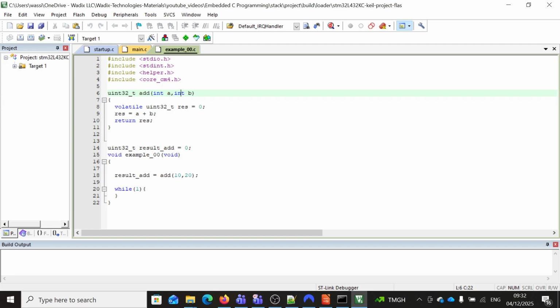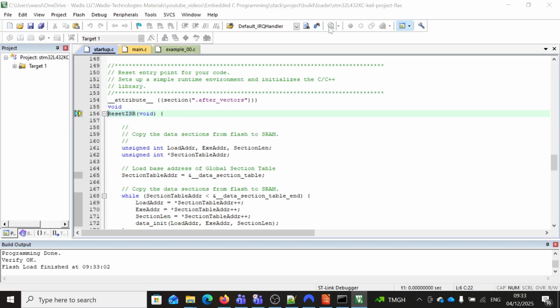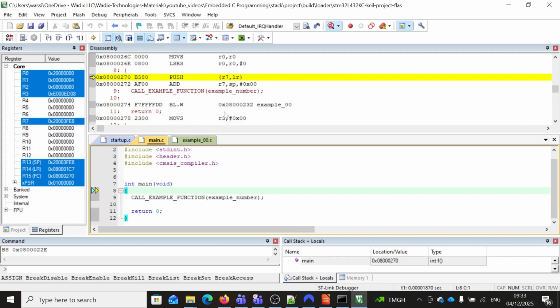We'll try here to highlight the impact of the push and pop operations on the stack memory region itself, and we'll see especially that the CPU stack pointer will always be pointing to the last element that has been pushed to the stack. So we load our binary into flash memory. Then we start a debug session on the binary that has been loaded into our STM32 microcontroller.